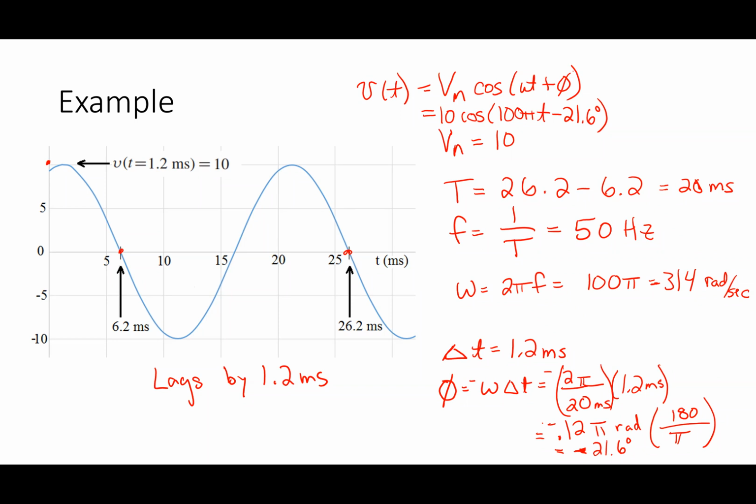You have to be careful about this, because if you went into your calculator and put in cosine 100 pi t, and you want to evaluate it at 1 second, and your calculator is in degree mode, you're going to be all kinds of screwed up. In general, we're not going to be dealing with things in the quote unquote time domain like I have right here, but we'll see some examples of that as we go through.